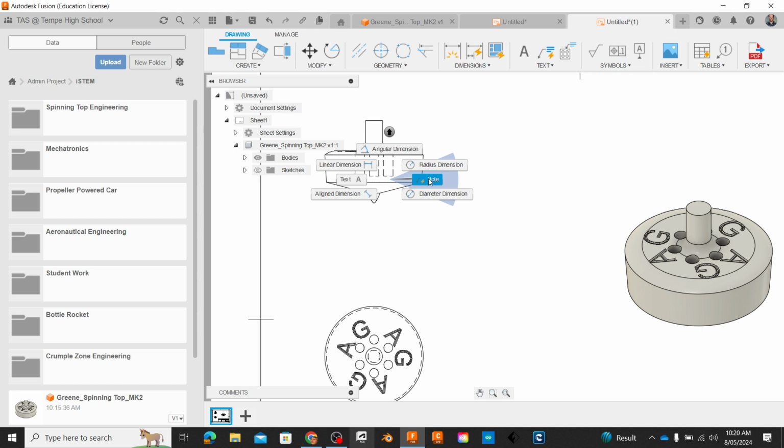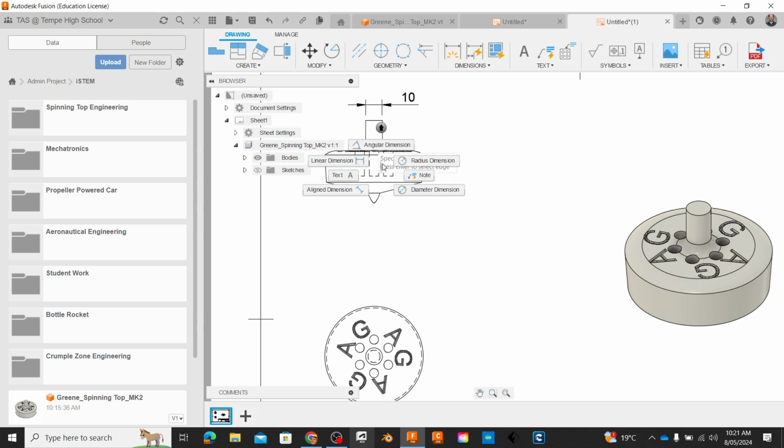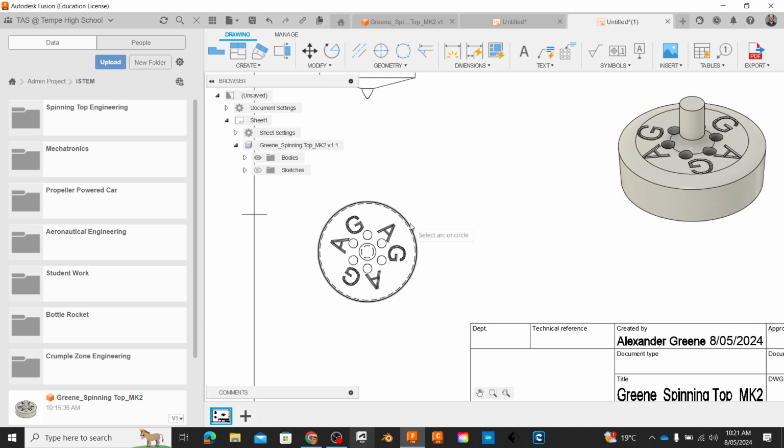So we'll go back through some of the dimensions that we discussed before. So linear dimension, I might want to go to this width again, even though it's the same as before. So I'll right-click again. You can go repeat linear dimension, or you can go to annotation menu and choose a different thing to annotate. Okay. For radius dimension, I might put that down here or on the outside. So what does the R mean? Radius. Yeah. Radius 29.73. So that's half of the diameter. All right.